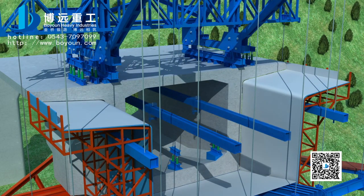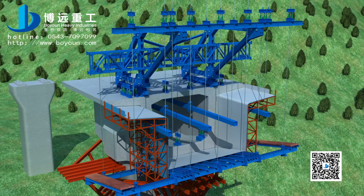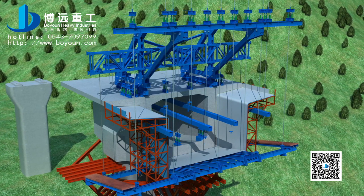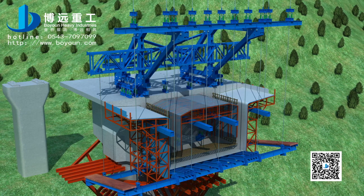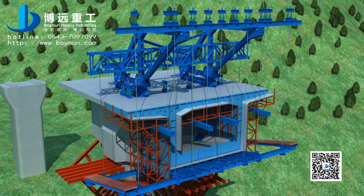Install and fix internal nose girder. Bind girder section reinforcement. Install internal formwork, end formwork, cast concrete, and maintain until casting the next section.